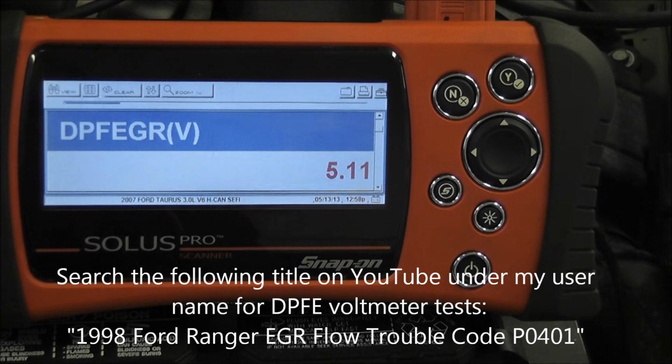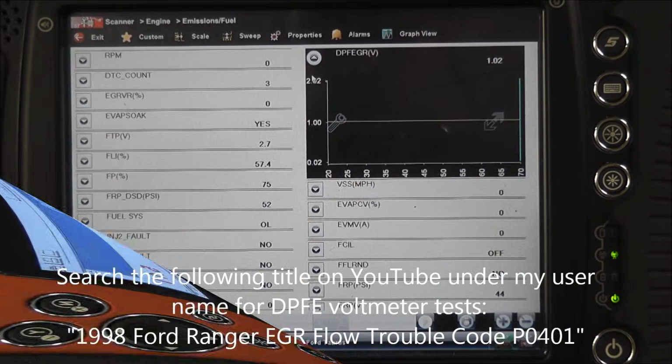Not necessary on this one, but if you didn't have a scan tool to do this, you could certainly do voltmeter checks at the sensor itself and do the same exact thing that we're showing here, which is unplug it. If you're at 0.13 of a volt, you unplug it, that signal wire should jump to 5 volts, and that's confirming your circuit integrity right there. So it is able to be done with a voltmeter too. And some of you guys get on me with my fancy equipment. All you need is a $10 test light and a $20 voltmeter and a couple of T-pins, and you can diagnose this car with this problem.